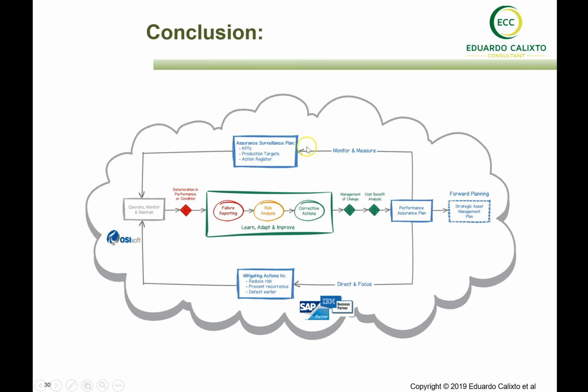And of course, you constantly track your KPIs based on online monitoring, and whenever you need to mitigate the risk, you look at your KPIs as well to see the effect. The point is, based on such an approach, based on inspections and non-destructive tests, you need to start to see some degradation and get some points to be able to predict the remaining life of such equipment.